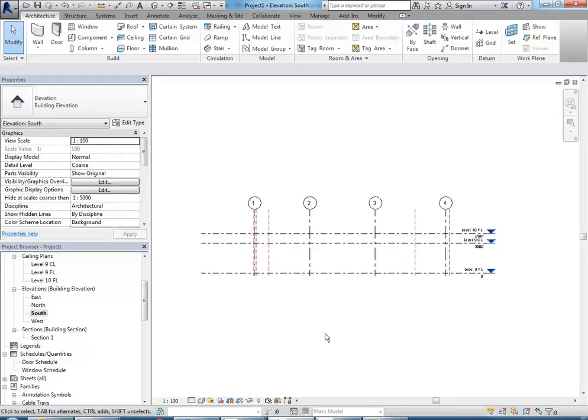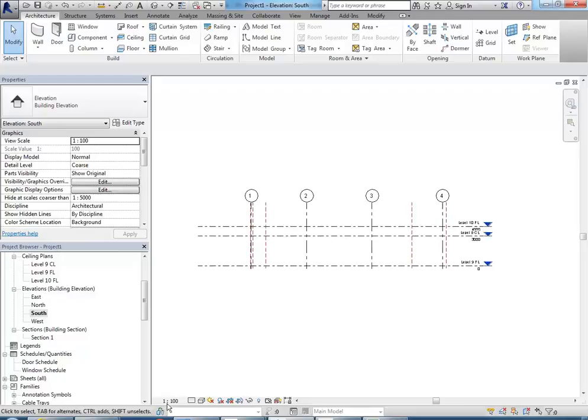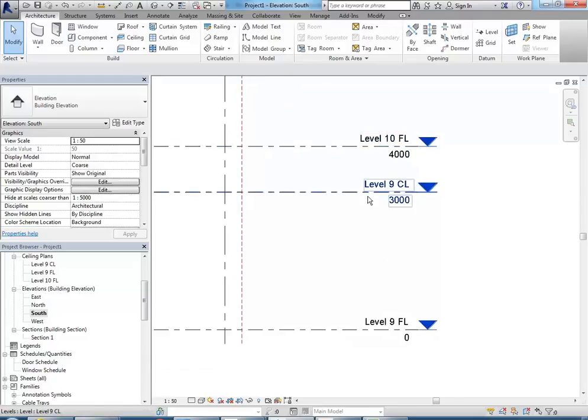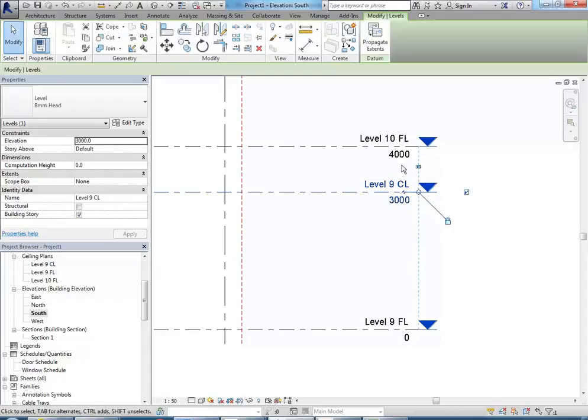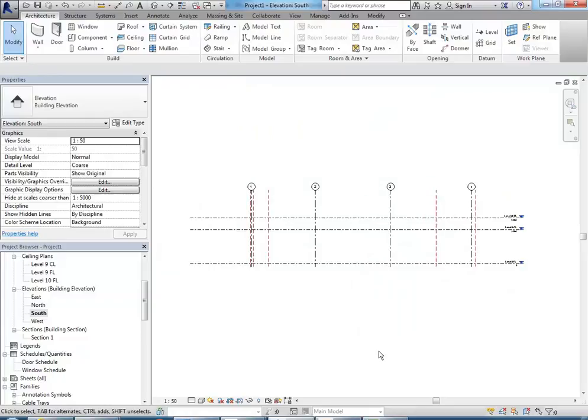that's basically good enough for me to start working on the physical elements, walls and floors mostly at first. I'm just going to do one extra step though to make it easier to read those numbers. Mainly, I'm going to change the scale to 1 to 50. So it'll make the text smaller and then won't overlap. I know I showed some of you that you can adjust the height of those tags, but sometimes it's easier just to change the scale. So that's it for now, and then next time we'll have a look at setting up your walls and floors and other things like that.